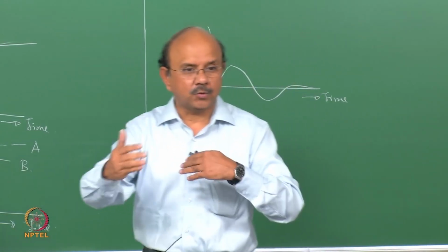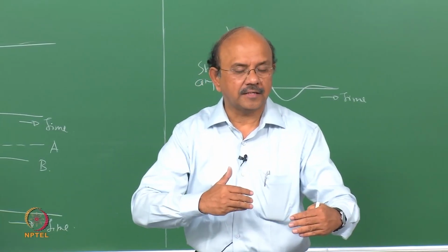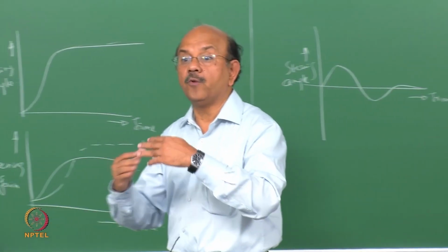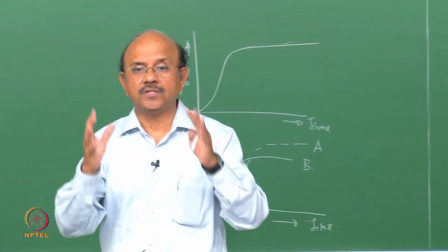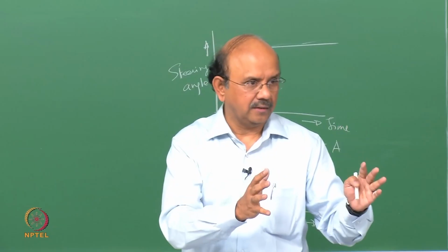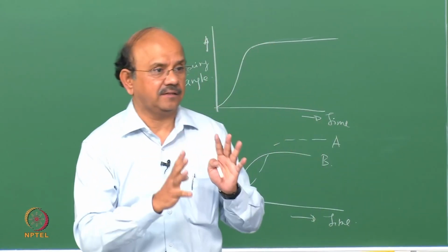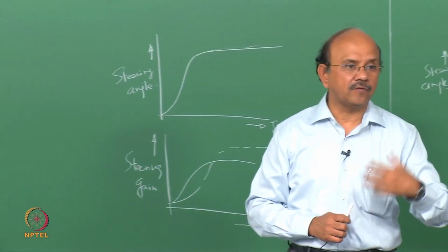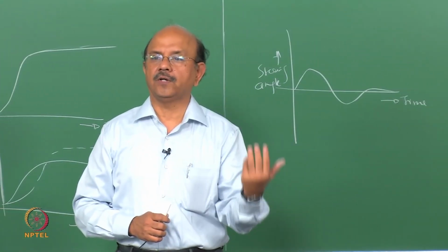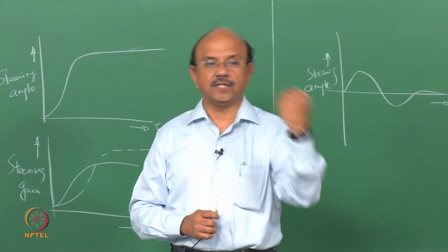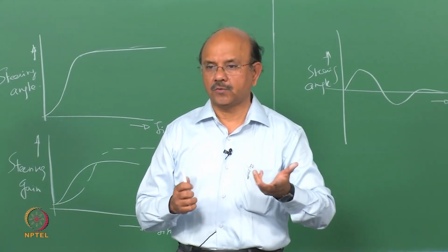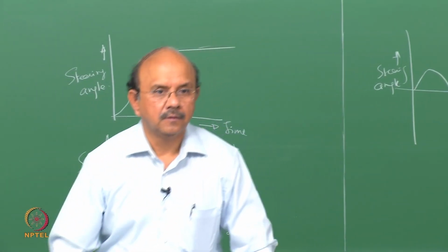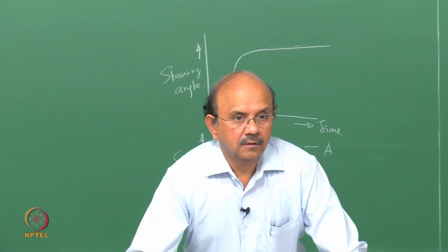So whenever there is a transfer like that, alpha F, alpha R gets affected, and hence I get a variation in the oversteer or understeer characteristics of the vehicle. This is what is tested: what happens when I power on and power off in a turn, and how much the vehicle is going to become understeer or oversteer because of this transfer of power. Clear?